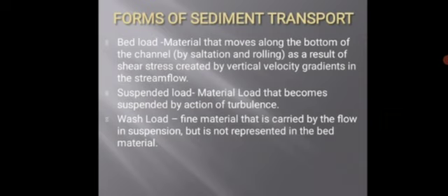Next, the forms of sediment transport. At first, the sediment may be transported as bed load. Bed load means material that moves along the bottom of the channel by saltation and rolling processes, as a result of shear stress created by the vertical velocity gradient in the stream flow.